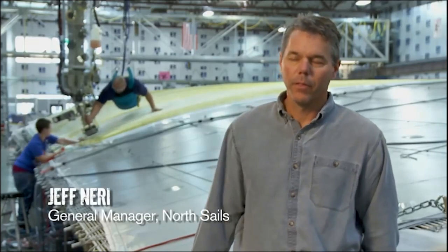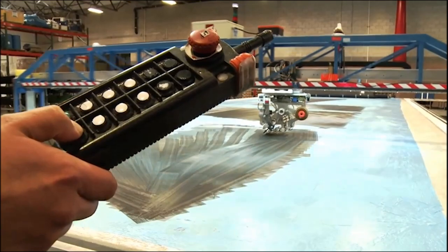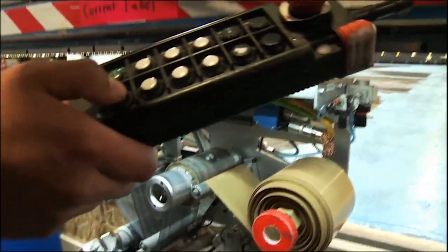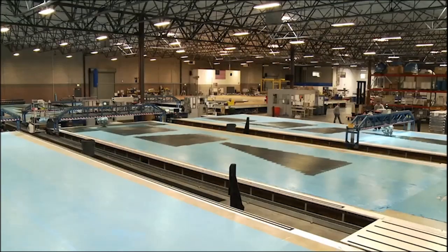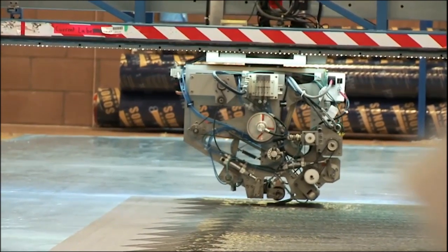I mean, the 3D is kind of the key thing. We mold sails in 3 dimensions, so we get a truer flying shape building them that way. 3Di is tapes, much finer resolution, much higher resolution. We can control where we put the fibers, control the weight, we control anything we want. The main objective is to make a really durable sail that holds its shape and stays together for as long as the race needs it to stay together.